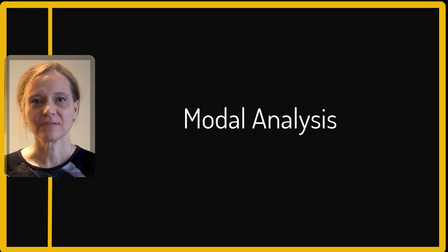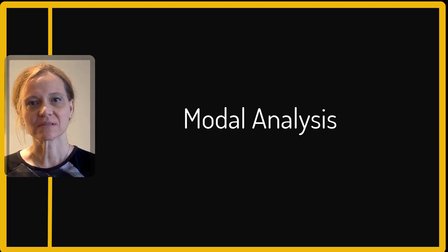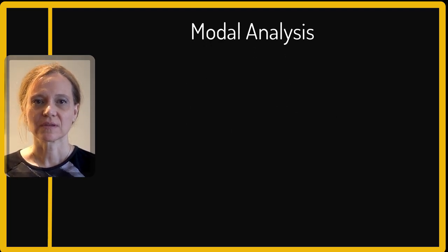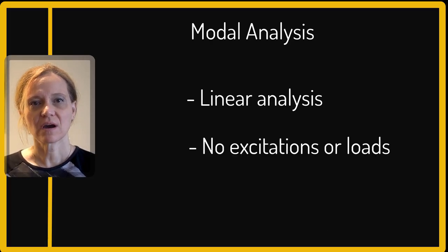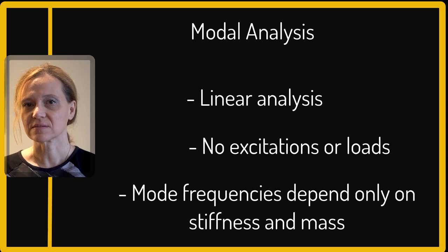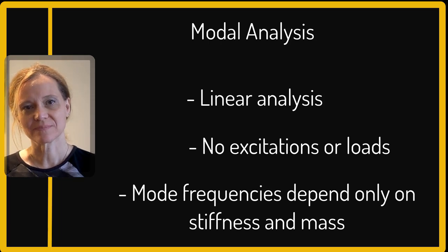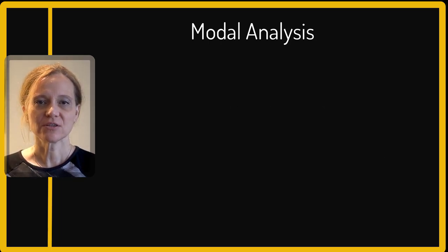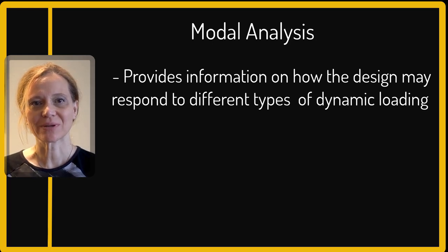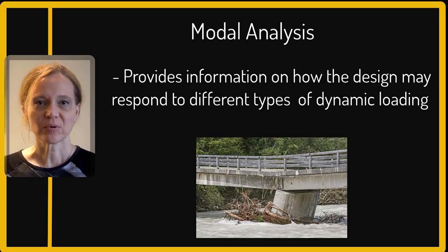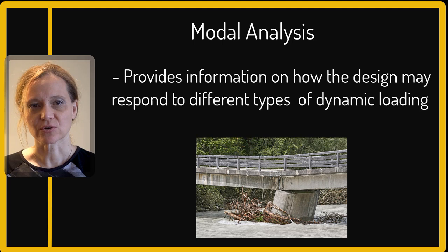Modal analysis provides valuable insight to the dynamics characteristics of the structure. It is a linear analysis that doesn't utilize any excitations or loads. Mode frequencies are dependent only on two things: stiffness and mass. Modal analysis provides engineers with information regarding how the design may respond to different types of dynamics loading and can be used, for example, to avoid resonant vibrations that can be harmful to the structure.